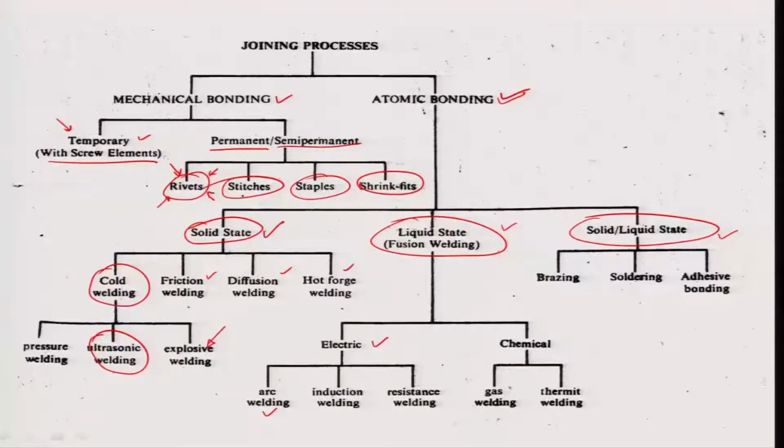So, the electric source can either be an arc, where you can record this as an arc welding process. It could be electromagnetic induction causing eddy currents, which would lead to the local heating of the material, particularly metals. Then other induction welding, or resistance welding, where there is a pressure as well as a strong current between the sheets that are being joined, or the two members that are being joined, which results in a local heat increase and a local melt pool between both the sheets.